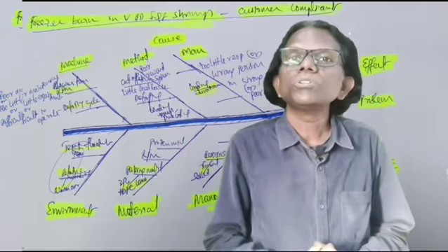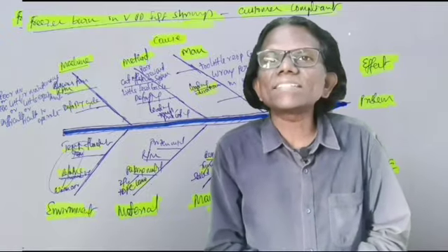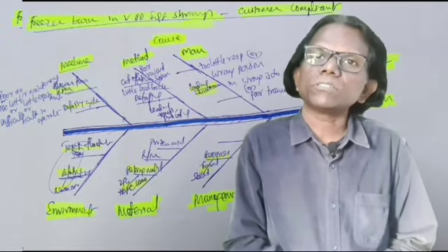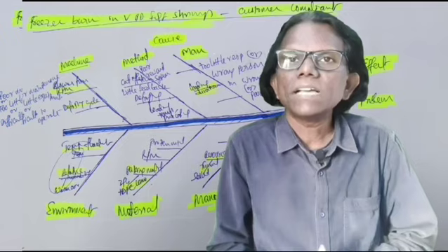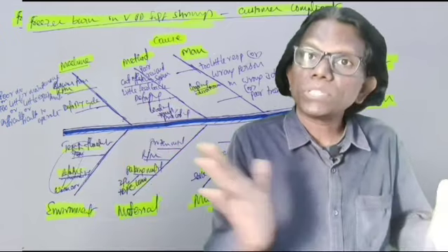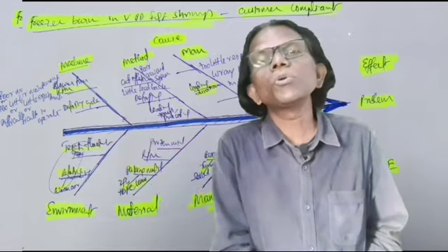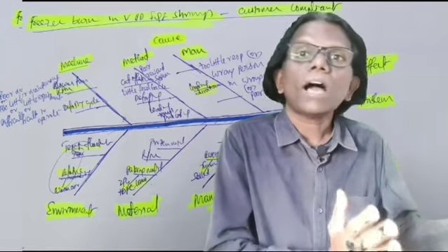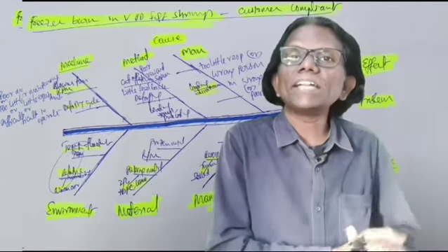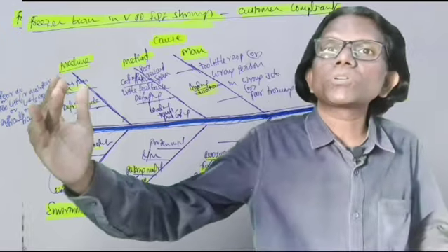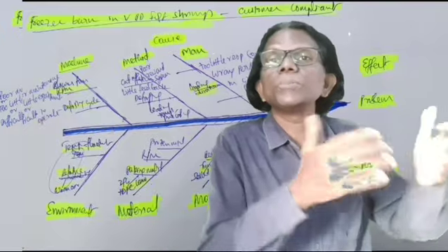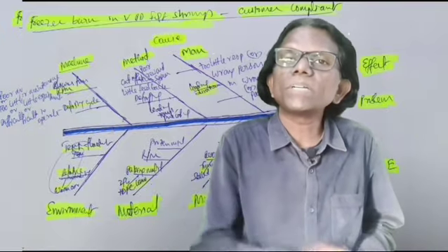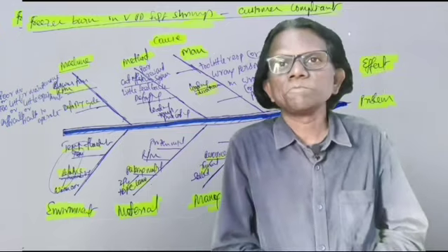Ultimately, the cold air cannot circulate to all corners of the cold storage, and defrosting cycles and running hours will increase. So environment also plays a crucial role, whether humid air or warm air is inside the anteroom. Once you open the cold store door, warm air may enter, or the relative humidity will come down, and then automatically more moisture is extracted from the product.